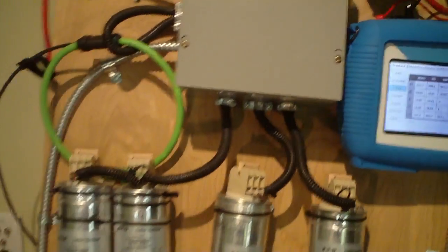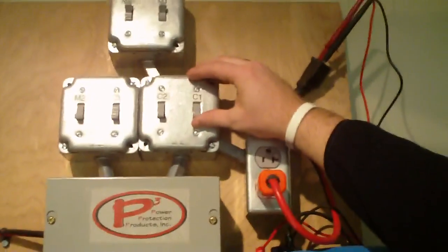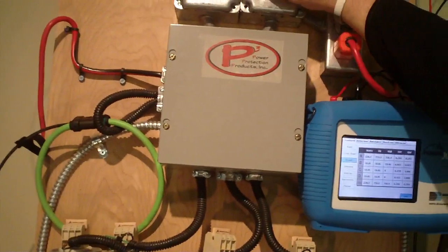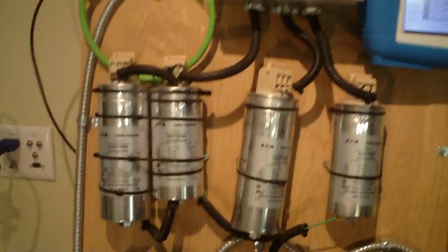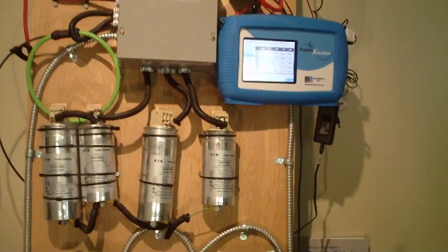And now, as I would like to correct this power factor, I will start to begin bringing on some capacitors, flipping on the first stage. Now that we have done that, you can see we've brought our power factor up with a minor improvement to 0.294. We still need to correct even further, so we'll engage another stage. And you can see that the power factor is now corrected to a 0.958. Very close to unity, what we'd also consider as a perfect scenario.